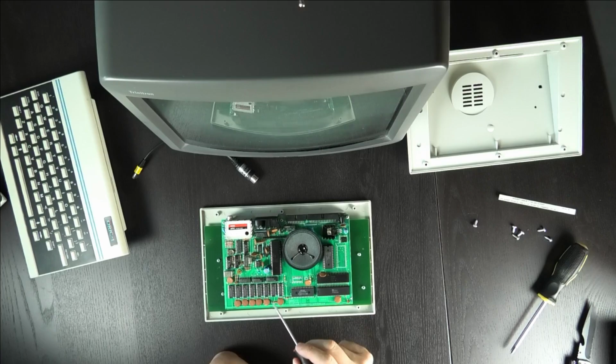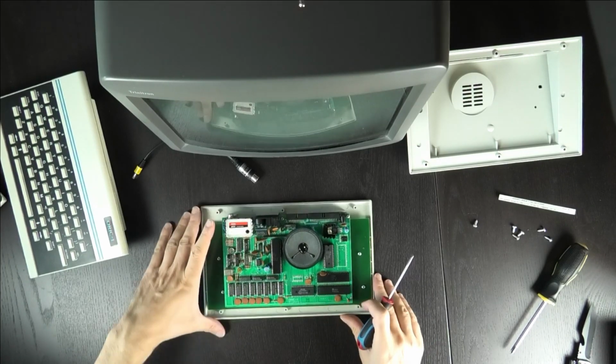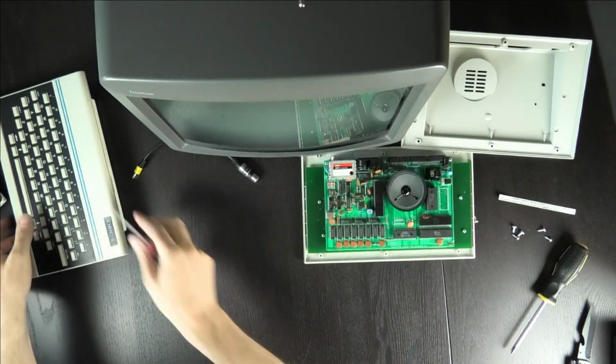And despite the Oric saying that it has 48K, it does have 64K of RAM. The reason they are sold as 48K is that these two chips are overlaid by the ROM, which is 16 kilobytes. So while the ROM is active, you can't access these two chips, but if you have a floppy drive, the DOS itself installs there, and there is additional hardware in the floppy drive unit to allow disabling the ROM chip. So that's 48K.